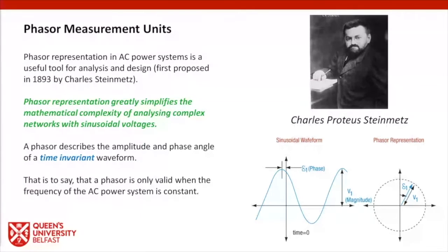But regardless of that, the point is that phasor representation greatly simplifies the mathematical complexity of analyzing AC systems. They're a fantastic tool. They reduce the information that we have to deal with from the time varying AC waveform to basically scalar values, well, obviously vector values, but they reduce magnitude to a scalar value, phase angle to a scalar value, etc. So we can now just apply vector maths to the problems, and that greatly simplifies our modeling and planning of power systems.